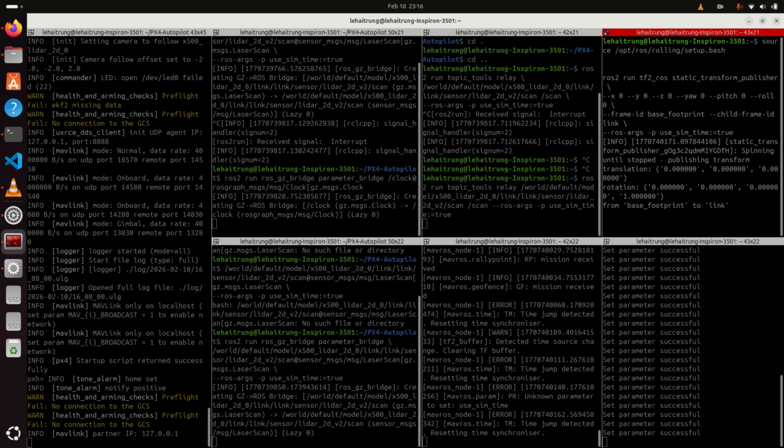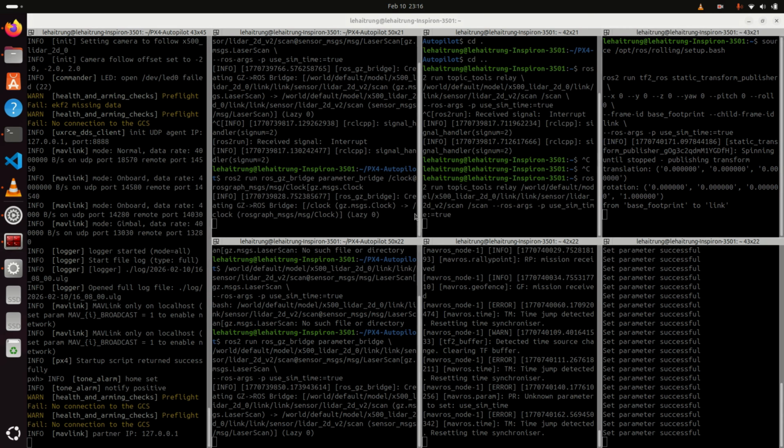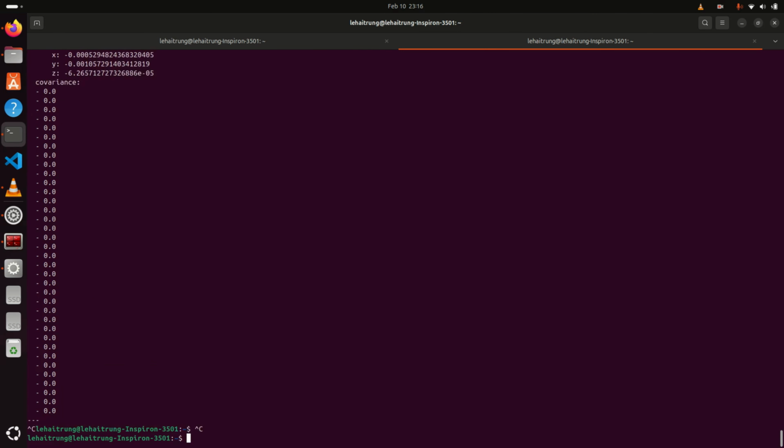Here you see that I use base_footprint instead of base_link, because in SLAM the frame of the robot is called base_footprint instead of base_link. You really need to check the relations, and you want to be very careful with these frames, because just a typo and everything will be disconnected. So now we can try to check the relation between everything using ros2 run tf2_tools.